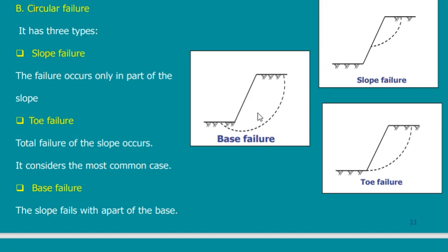And then I go to this one, I will calculate the weight of this new portion, and I will calculate the shear and the phi stresses along this line, and I get something less than 1, suppose 0.8.